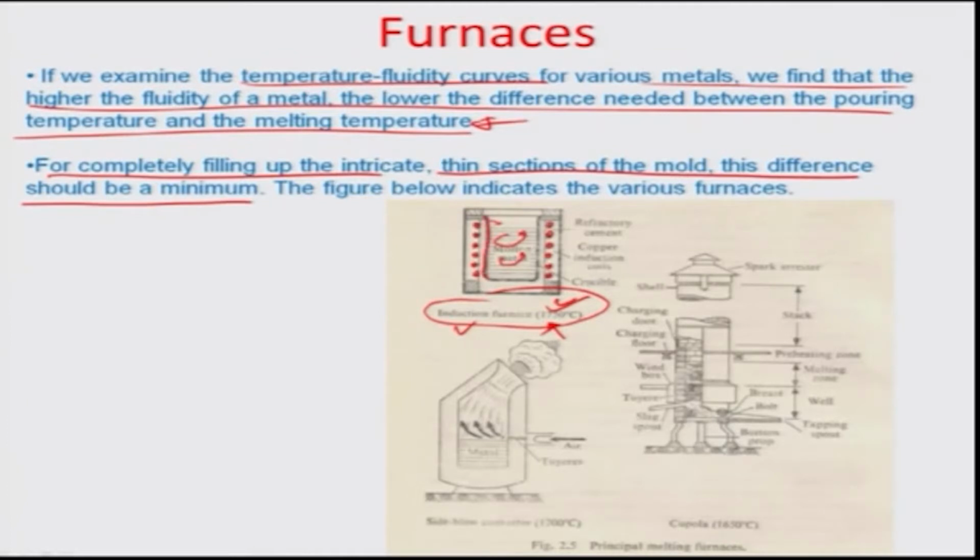So, the crucible can sustain the high temperature conditions where the metal gets into liquid state. There is a refractory cement which holds this crucible in place, so that the cement is able to expand and hold its strength at a higher temperature. So, whatever outflow of heat happens from the molten metal to the furnace can be protected on one hand, and on the other the strength can be kept intact, so that this cup does not vary in size or shape, or does not go down. So, that is how the induction furnace is.